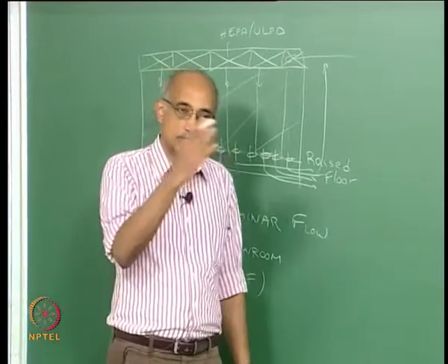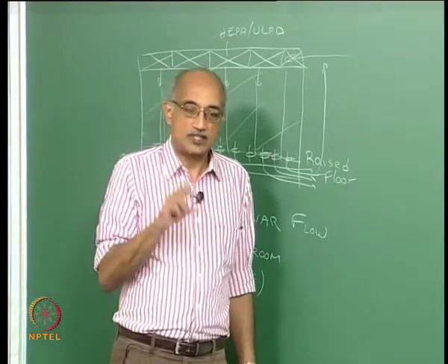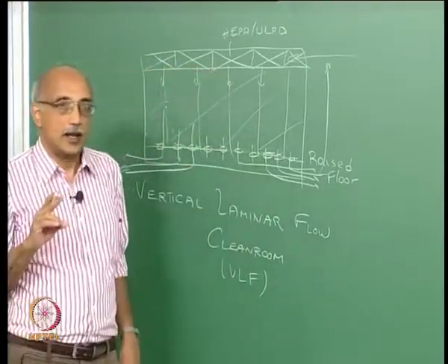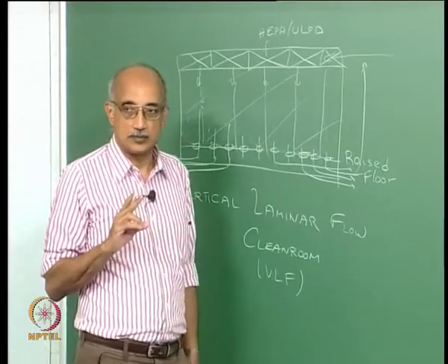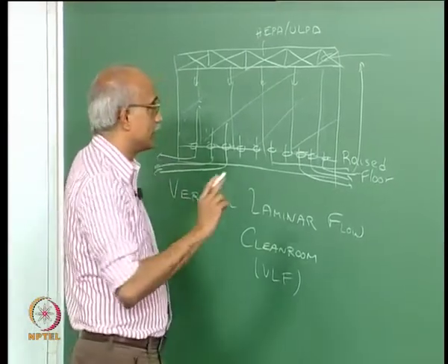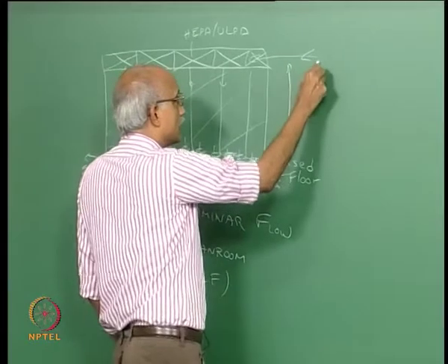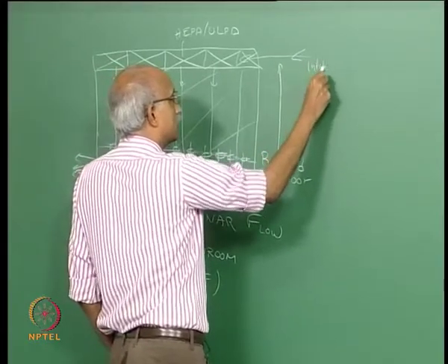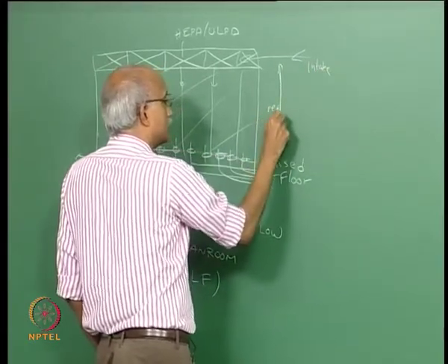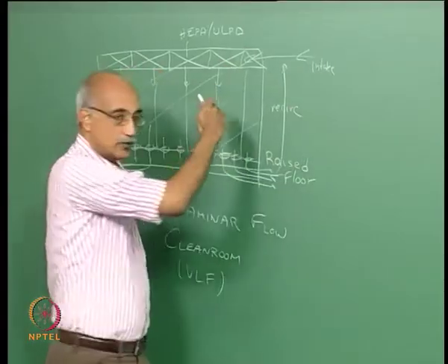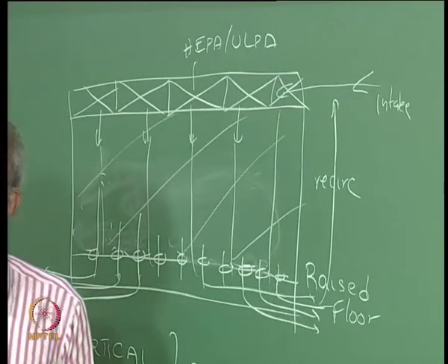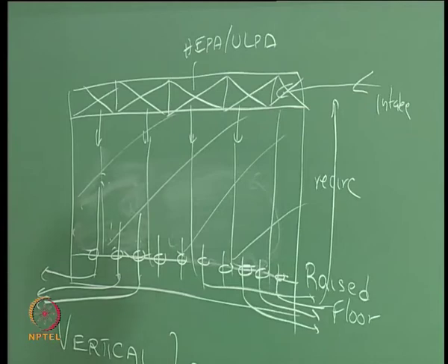So you build in a continuous recycle loop which minimizes the total air handling that your filter systems have to do. So it basically reduces your intake air. If this is your intake and this is your recirc, the total airflow into the clean room is the intake air, also known as the makeup air, plus the recirculated air.